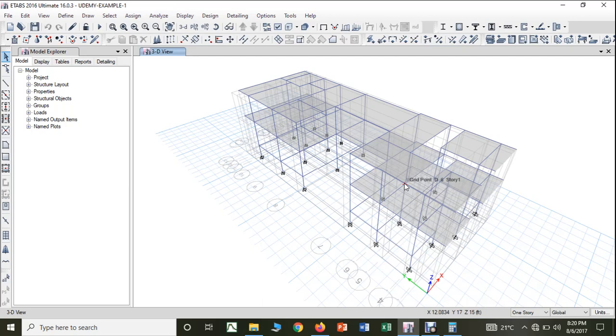And you know, the height of the parapet wall will not be the same as the height of the wall constructed below. Usually the height of the wall constructed in the floors will be around 3 to 3.5 meters, that is equal to your floor height. But the height of the parapet wall will be maintained around 3 to 3.5 feet, that means 1 to 1.5 meter.